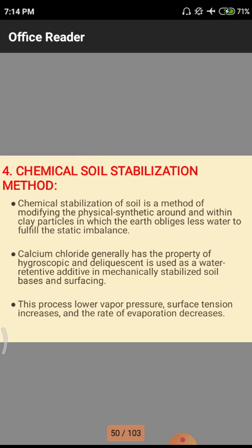Similarly, third, we discussed stabilization of soil using cement. In cement stabilization, we use a particular quantity of cement according to the condition of the soil and the particle sizes. By using cement, we simply get a crystallized strength. Normally in lime there may be bonding, and in mechanical stabilization there is densification, but in cement stabilization we form a crystal bond. Especially, cement stabilization is normally used below paved roads, so that we get a good compressive strength in the surrounding soils.